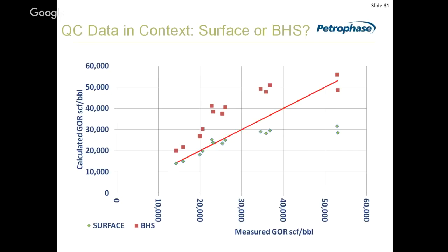Well, we can. What we can do here is we can take our flow periods, and each flow period, as it went through the separator, was operating at a different temperature and pressure. And that's not surprising, because the reservoir fluids come up. If it's flowing fast, it'll deliver heat faster at the surface. The separator pressure will be higher, and you'll get more flow through.